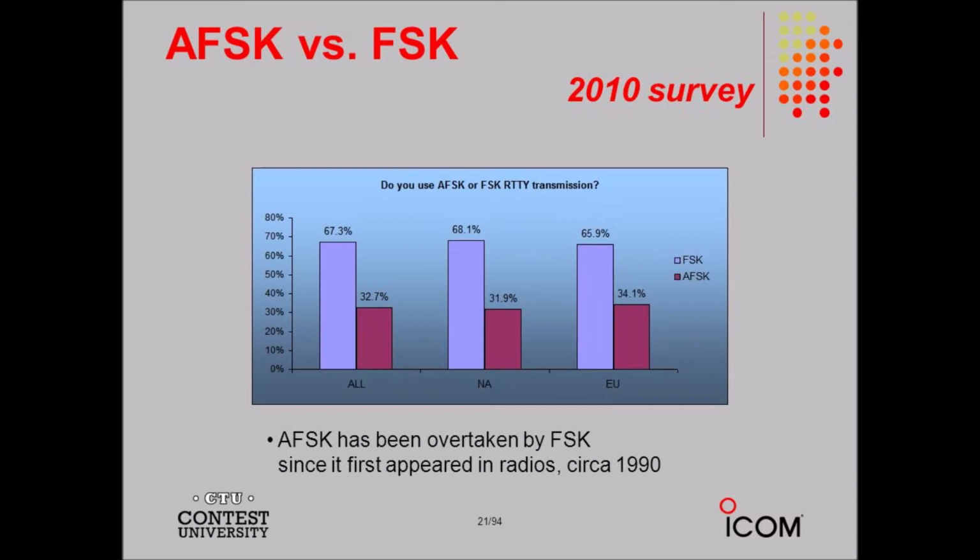Okay, continuing the reading, under the heading Amplitude Modulation on page 433, the second paragraph, the circuit shown in figure 25.2 performs well as long as we don't let the AF input amplitude become too great. If we inject too much audio, we get distortion, nonlinearity in the transistor, resulting in degraded intelligibility, understandability, reduced circuit efficiency, ratio of useful power output to DC power input, and excessive output signal bandwidth, the difference between the highest and lowest component frequencies.